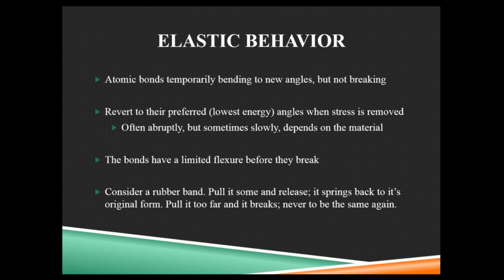Now, bonds have a limited range that they can flex. Different bonds have different ranges, depends on the molecule. But if they flex too far, they will break. It's like the rubber band. If you pull it a little bit and then let go, it'll spring back. If you pull it really, really far, it'll break in half. It's never going to be the same again. You can't release the stress and have it rejoin back into one piece. It's broken. That's brittle behavior.